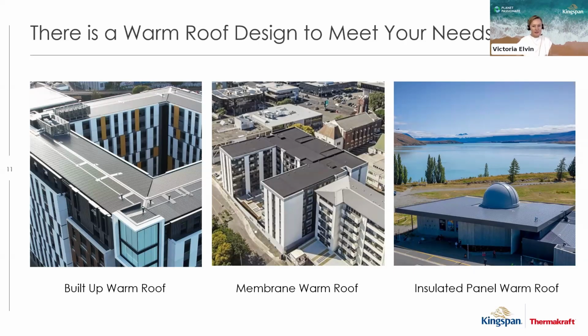An insulated panel, as you know, we do have Kingspan insulated panels as part of our portfolio, is also a one-stop shop for warm roof design, where the lining, insulation, and enclosure are all one. Now, of course, traditionally, panels have been limited to a particular length that could be imported, but now with New Zealand manufacture, we can see lengths of up to 24 metres, which makes designing with an insulated panel a little bit easier than it has been in part.